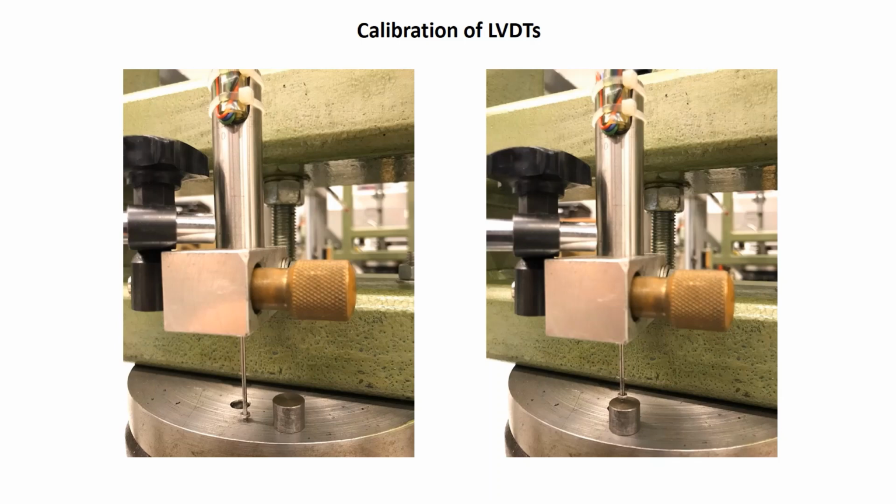And by knowing the exact length of the gauge block, we can find the sensitivity of LVDTs. We usually use a couple of different gauge blocks with different lengths to find the linearity of LVDTs, and also to take an average of different values to find a better and more accurate sensitivity.